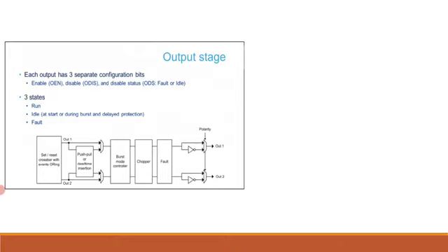The bottom figure is an overview of the whole output stage for a given timing unit. Following the set or reset crossbar, output 1 and output 2 reference signals can first be altered with the push-pull and dead time insertion unit. In push-pull mode, output 1 and output 2 are alternatively in run or idle states. When dead time is inserted, the output 1 signal serves as a reference to build the quasi complementary signals, and output 2 signal is discarded.